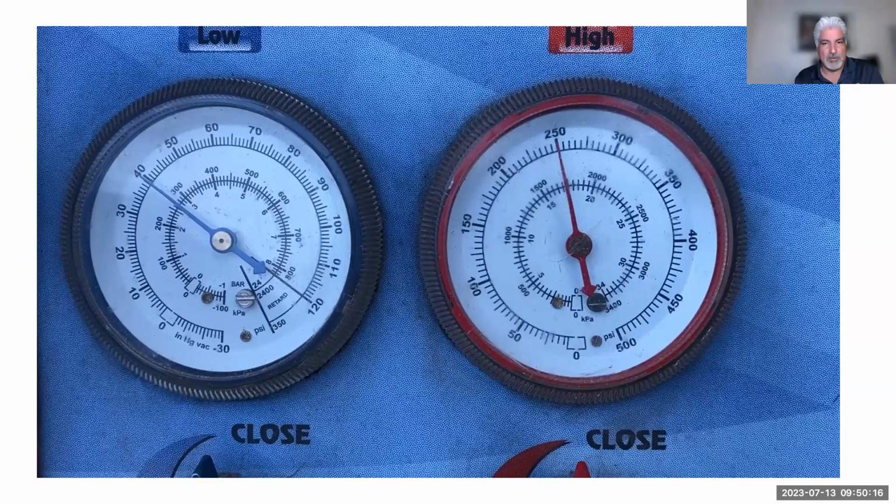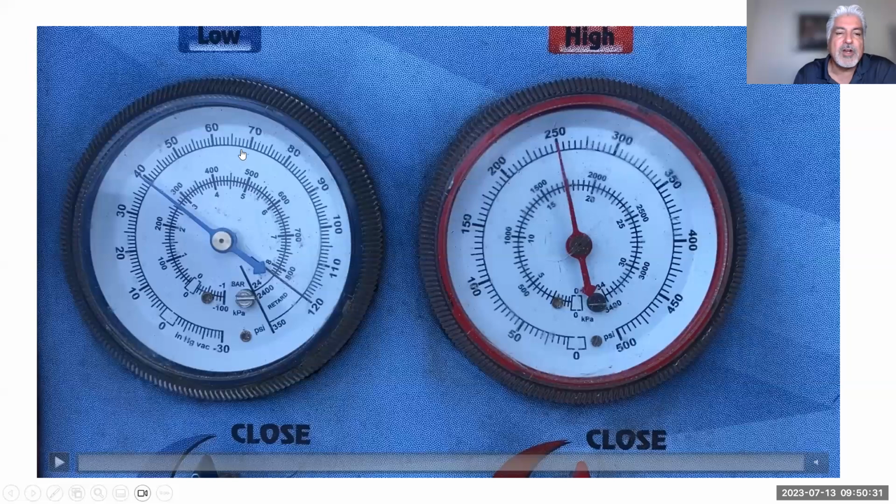Now, obviously, we're going to get some freaky stuff. This is normal. Now, the freaky stuff will be that the high side goes up and down, up and down. It just trembles back and forth between 250 and 275, let's say. Or the low pressure does the same thing, where that gauge is moving back and forth. So initially, when you first start off, you're going to look at the pressures where you start out and the pressures once the vehicle starts to warm up.